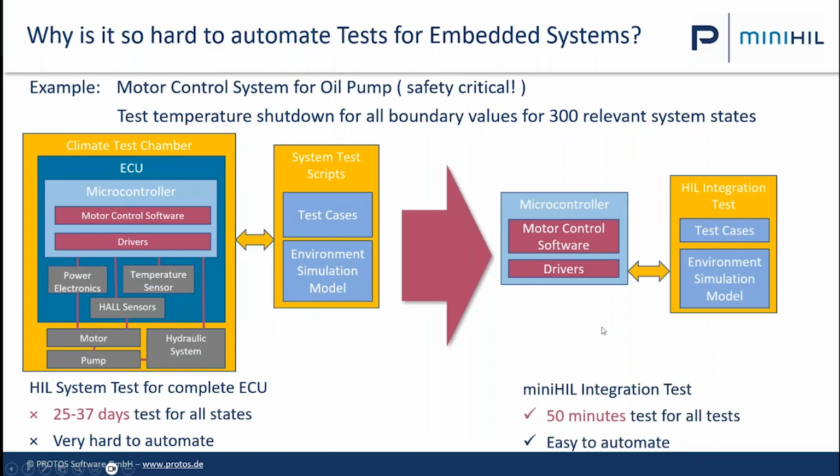What we did in this case, we took our miniHIL approach. We took the real microcontroller with the complete motor control software and the drivers. We integrated it into our hardware-software integration test with the test cases and environment simulation. And suddenly you get down, in this case, to 50 minutes for all tests, including all the other tests of the system, so not only the safety-relevant tests.